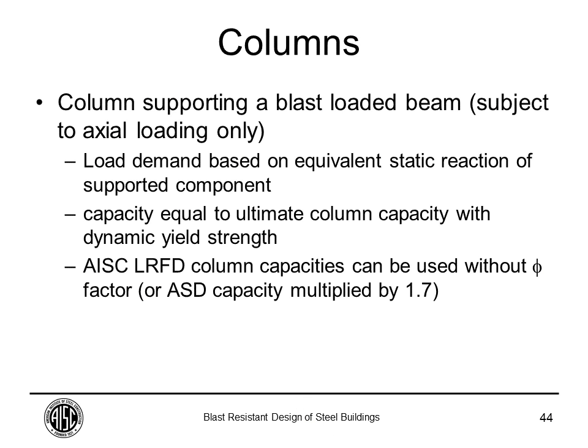So now let's talk about columns. We mentioned that in terms of designing a building to be blast resistant, you're going to be looking at your exposed members, which generally are the roof, maybe some perimeter beams, and occasionally you're going to have columns. Columns may be loaded in two different ways. The first approach for columns is when you're looking at it for axial capacity. You can picture a top-level column that is resisting a blast-resistant roof.